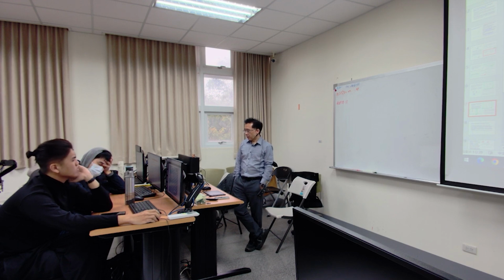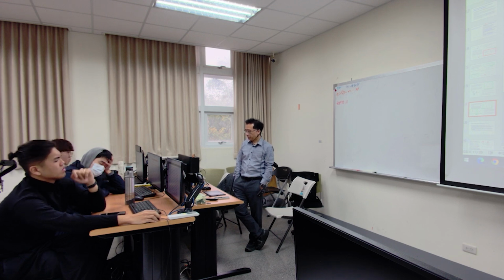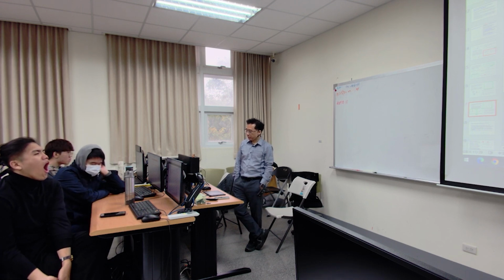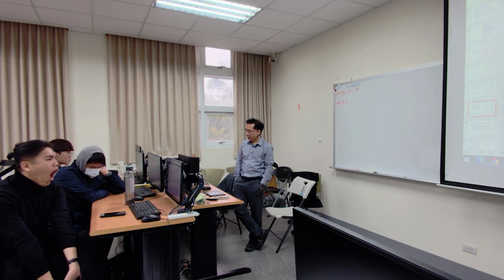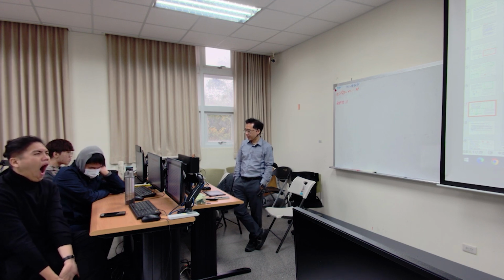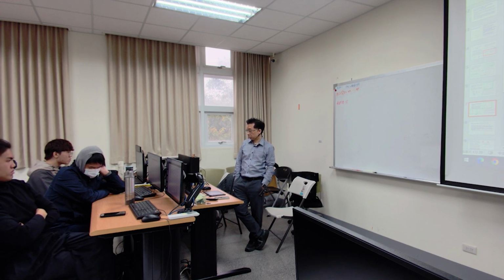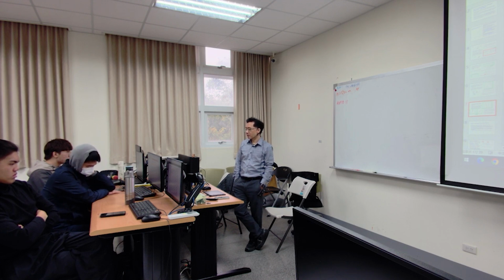The parameter a is the distance between Z0 and Z1. Okay, we know the arm length. How about alpha? I will explain alpha in more detail. The angle alpha is the angle between Z0 and Z1, measured in a plane normal to x1. So you rotate about x1, okay.